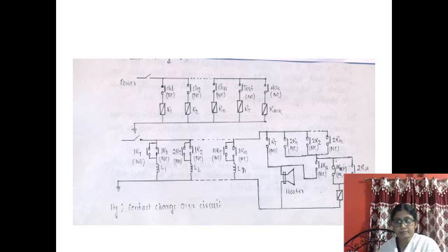So without energization of this RH, there is no function of changing this position. So this is in break condition. So again, as this is in de-energized state and this is normally closed contact of this relay, so this path is in make condition. So Hooter circuit will make and the audio signal will be produced.